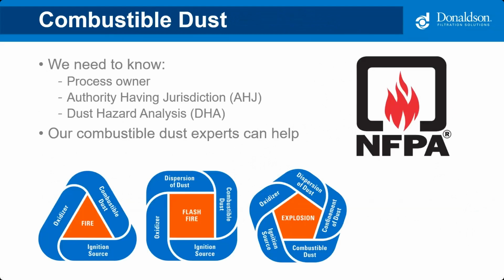And speaking of explosiveness, it's important to know that some dust and fumes may present a combustion risk. If the dust or fume is combustible and it mixes with air, like the airflow coming into a dust collector, and an ignition source, the end result could be a fire. And if you add the dispersion of the dust, which occurs frequently in a pulse cleaning collector, you could get a flash fire.